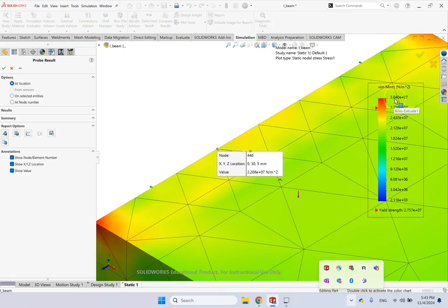How much was this max? Look, right now it's about 30. Last time it was 70. Do you see? So I made the mesh bigger. I'm around 21, 22. My max is 30. If you go back and look at the video, just move back a little bit. The same region with finer mesh was still around 20 something, but this hot spot was around 70.